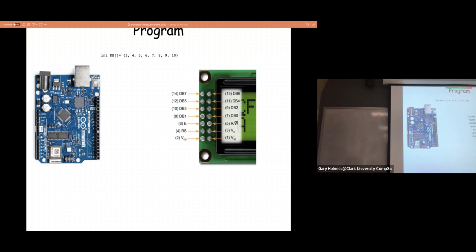And so here we have the pin numbers, and these pins, as described here, each column represents the odd number signal pins for the device. And this next column, the right-hand column, represents the even number. So we have the evens and the odds, and when we count them, we number them row major from right to left. So this is pin 1, 2, 3, 4, up to 14.